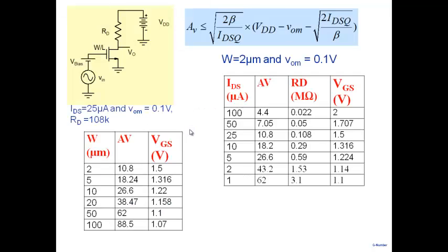Okay. So this is telling you that getting large values of gain is difficult from this particular stage, a common source amplifier with a resistive load. And therefore, if you want higher gain without requiring a large value of resistor, what is the way to do it? What do we do? I don't want to use a very large value of resistor here because it's difficult to make. So I should replace RD by.